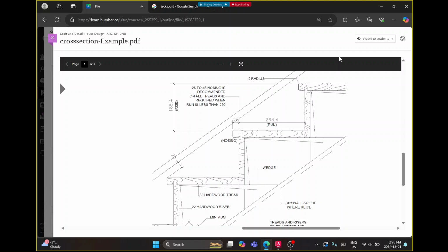But plywood is made up of 1.5 millimeter thick layers of wood glued together. So as soon as you sand it, you're going to expose the other layers beneath it, and it's going to look very strange. So it's almost always solid wood here and solid wood here.